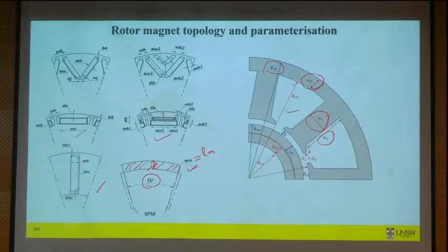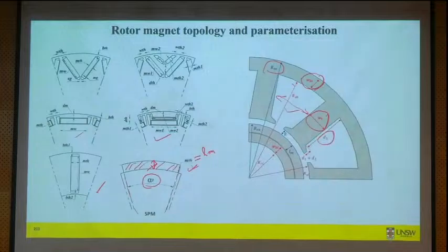Okay, for example, this rotor outer diameter and your tooth width and slot width, they depend on each other, right? If you make it bigger, you will have more space for them. So, considering this as a geometrical object, dependent parameters can be separated out, and you can simply select only the independent geometrical parameters for your optimization and make the number of variables a little bit less.